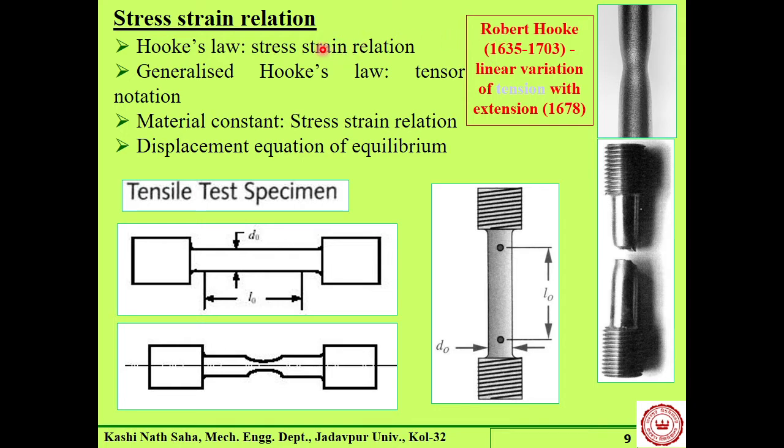But now we have seen that our stress and our strain are not a single quantity. That means they are not necessarily linear, meaning unidirectional stress or strain. There are shear stress, shear strain, etc., and the stress and strain are represented by a 3 by 3 matrix. We call them the stress and strain tensor.